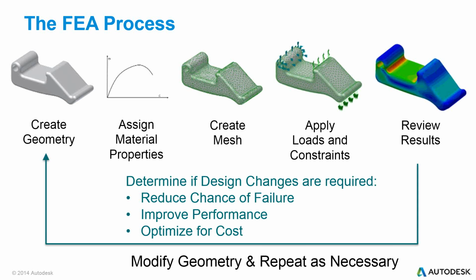It's take the time that's required to take that production-ready CAD geometry and make it into something that's more simulation-ready, where you're not worried about the individual microscopic details unless they're an area that's causing problems. So if you have small fillets or chamfers, small surfaces and such that are needed for production purposes, but really aren't bearing the load, whatever kind of load it is, a lot of times the analyst has to spend a fair amount of time cleaning up the geometry.